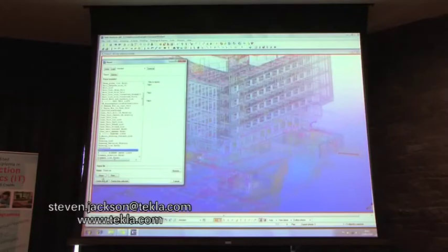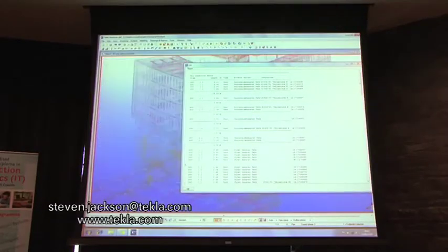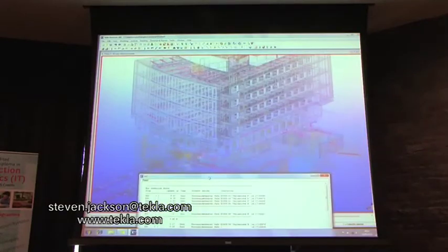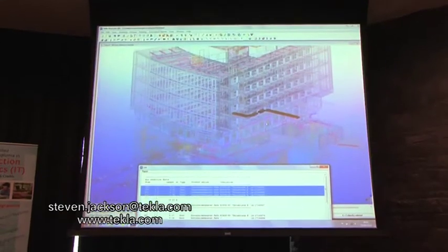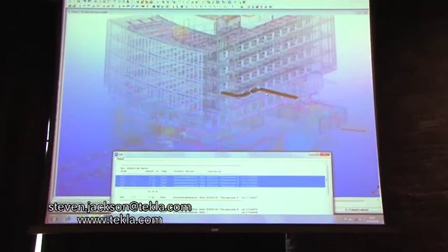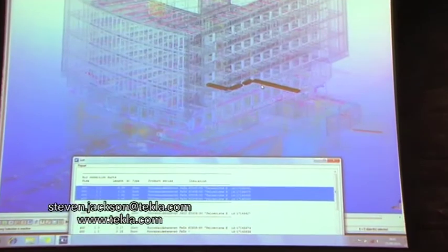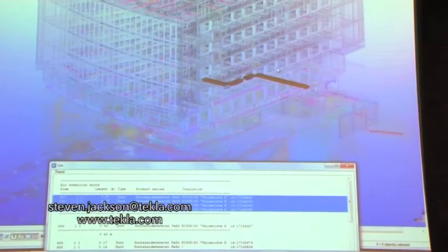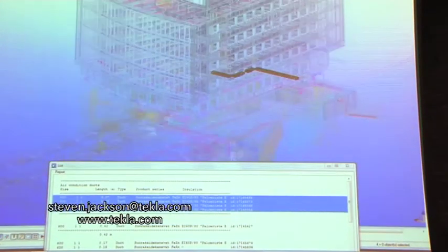If I come down to the ducts and show you this list, there's all the duct work, so 600mm ducts. I've got a length of 9.37 meters. There's a product series. And of course with Tekla, what you can do is highlight these in here and it actually picks them in the model as well so you can find them. So you can quantify everything required for the HVAC side and for the heating and plumbing side as well, as the actual native Tekla Structures objects.